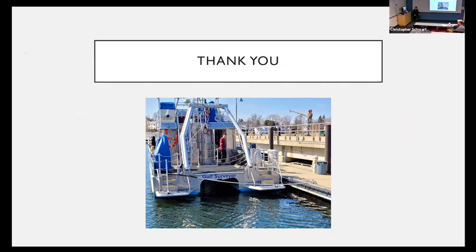So what would cause it not to generate good data? Oh, lots of things. People install non-rigid mounting systems for transducers, or they install them in places where they suffer from aeration from the vessel hull or the propellers, etc. Yeah, if the transducer was mounted closer to the center of gravity of the boat, that would probably be most ideal.